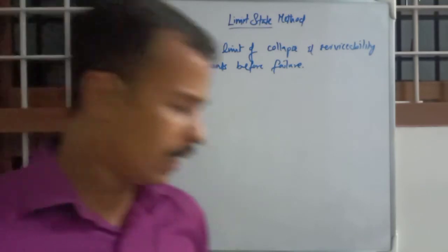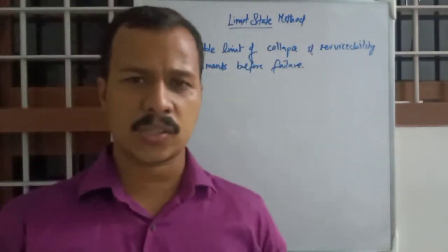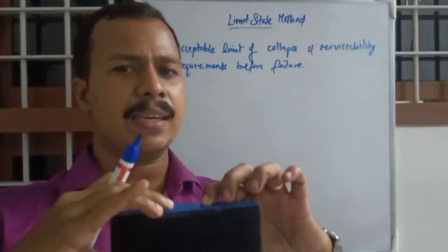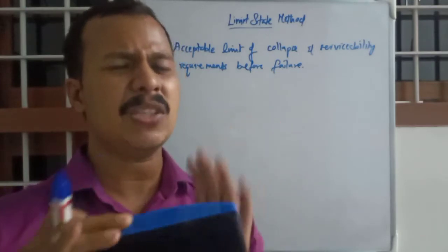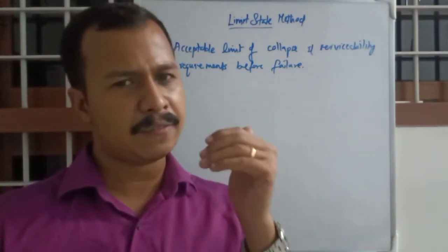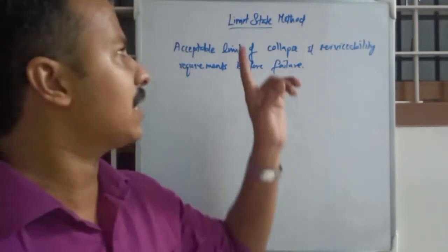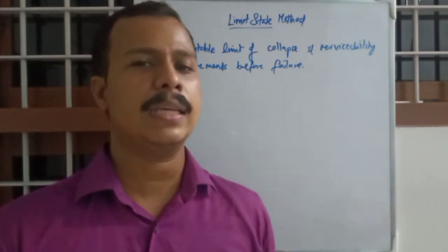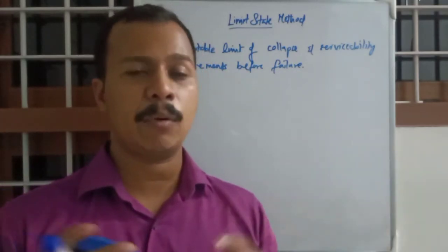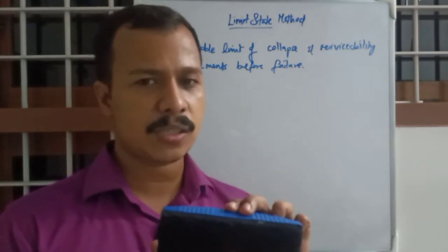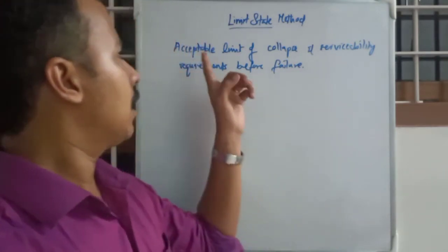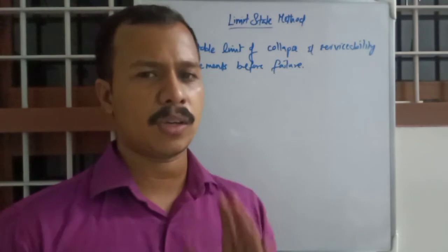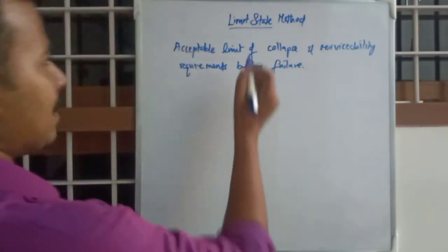If you take a beam or any concrete structure, just before breaking or just before failing, there will be a limit state. At the verge of breaking, and we are considering that limit state for designing this beam. So we will gather all the information and knowledge that we can get about the loads and the strength of this beam, and we will assume a limit state, and using that limit state we will design a concrete structure.